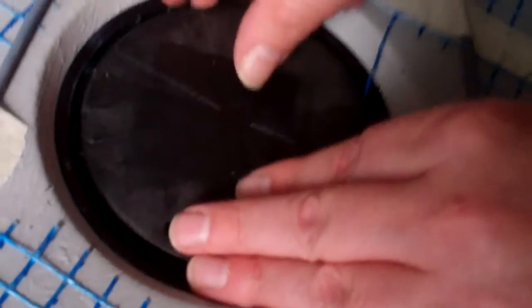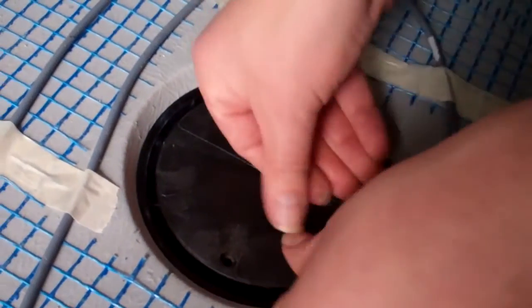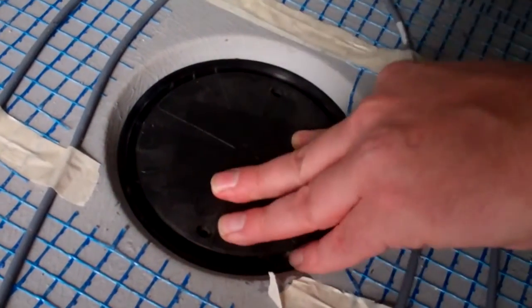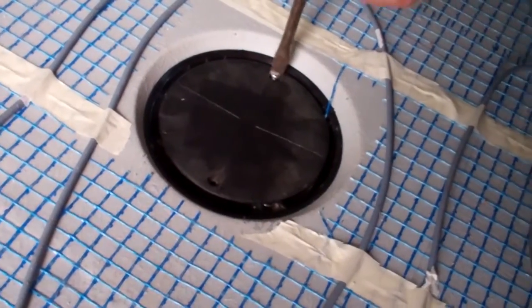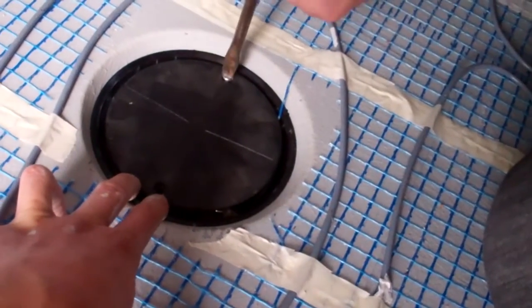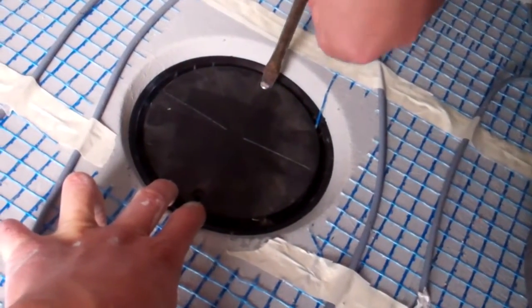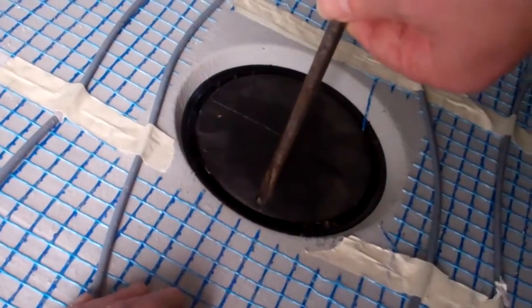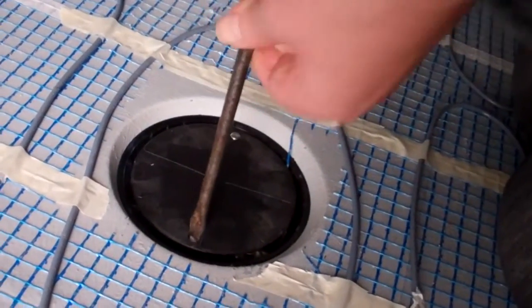Make sure the inner face of the waste flange is clean and free from debris, as the rubber gasket in the waste top will seal against this edge. Line up the 2 holes in the waste cover plate with the 2 remaining holes in the clamping ring and push down firmly into place. This is a tight resistance fit. Now secure the 2 supplied screws.